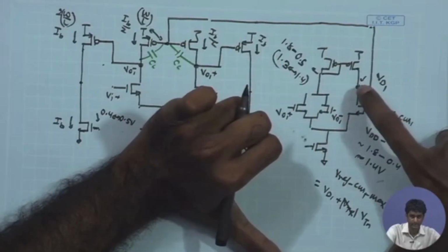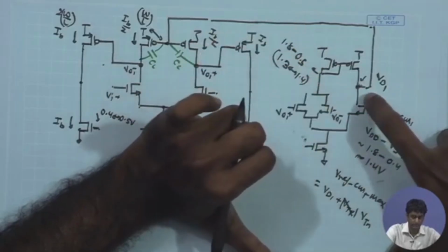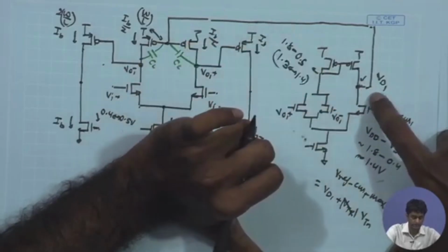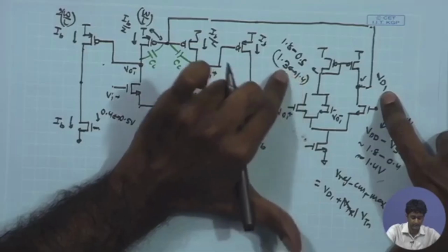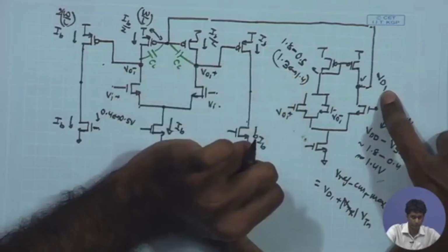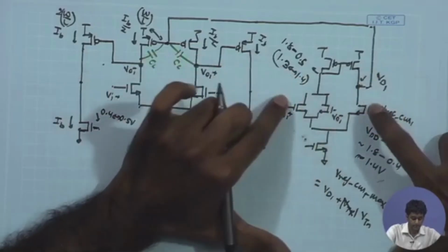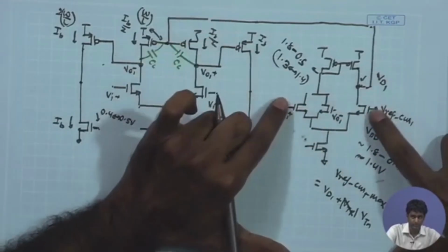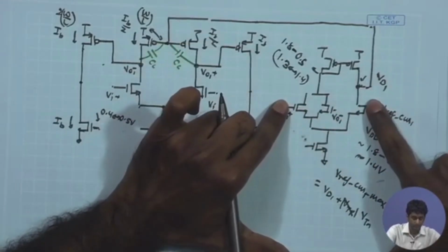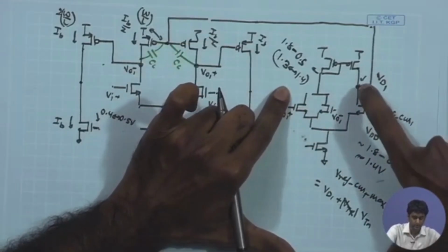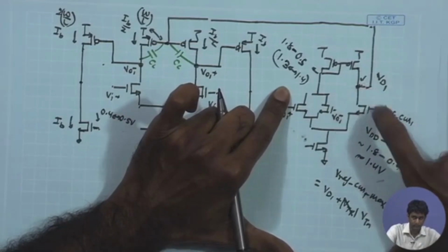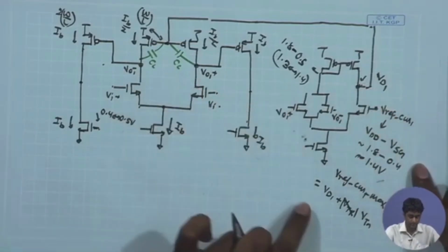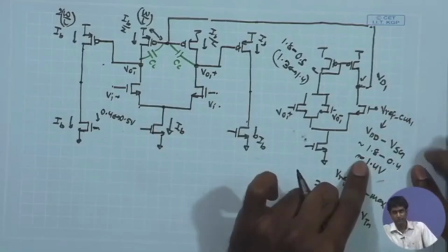So, I am assuming that under nominal condition, under steady state operation, the Vd1 is having a value close to 1.3, 1.4, and under that condition the maximum input level, the maximum common mode level for this amplifier that you can have, or in other words the maximum reference common mode level, is going to be the Vd1 plus Vtn, which is once again 1.3, 1.4 plus the Vt.